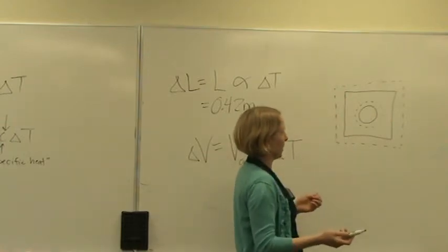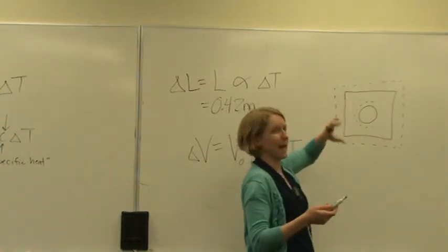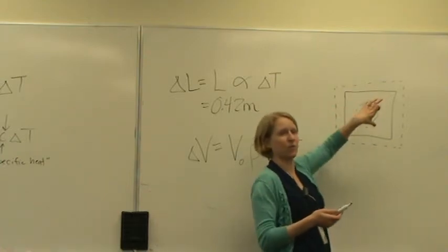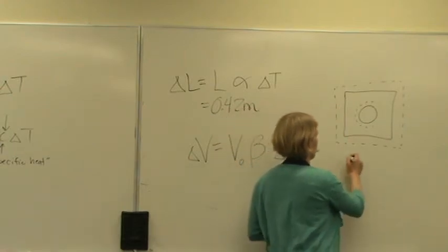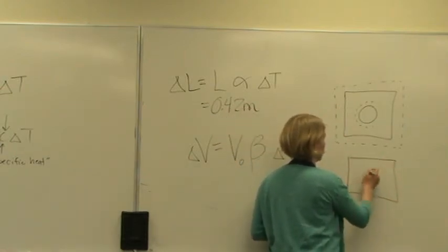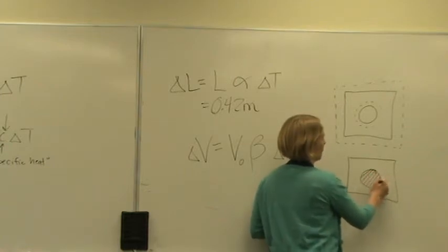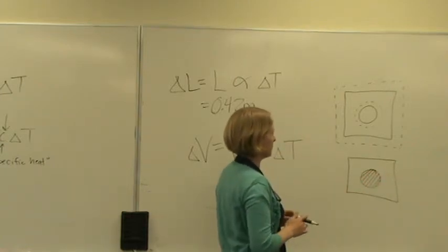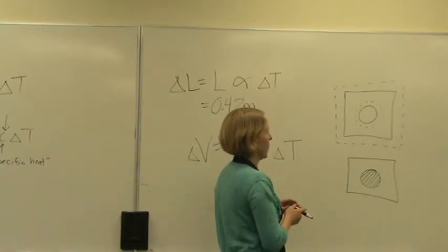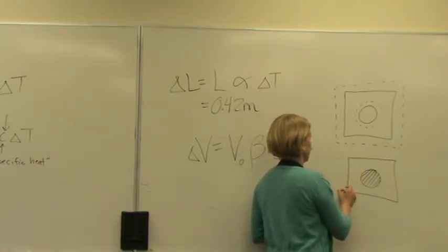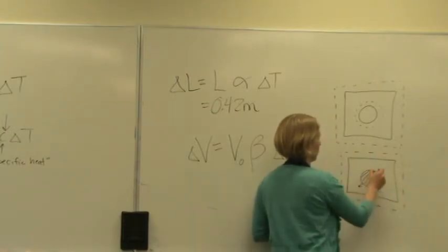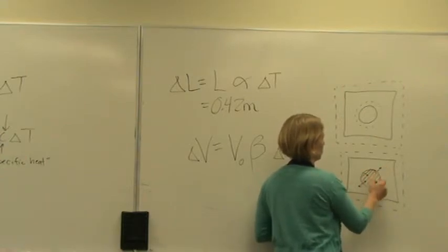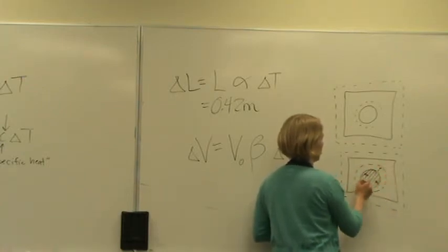And so if you think about, if you cut that circle out of the disc, or out of the plate, there is less metal in this object compared to a plate where this is actually missing, but the expansion happens the same way. So as this expands, it's going to extend outward, and the hole will go outward. It won't go inward, per se. So that's not happening. So it does go outward as it expands.